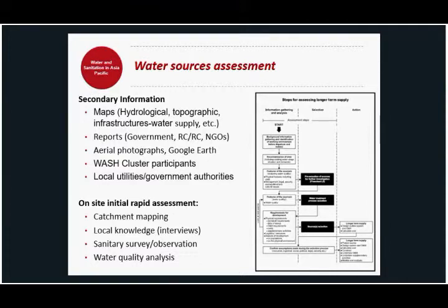Sanitary survey observation can investigate the local vicinity of the source and risks of fecal pollution. These risks relate to present and future scenarios. All surface water sources will fall into the high risk category, but the questions should still be answered to identify which of the risk factors are present or which can be improved.